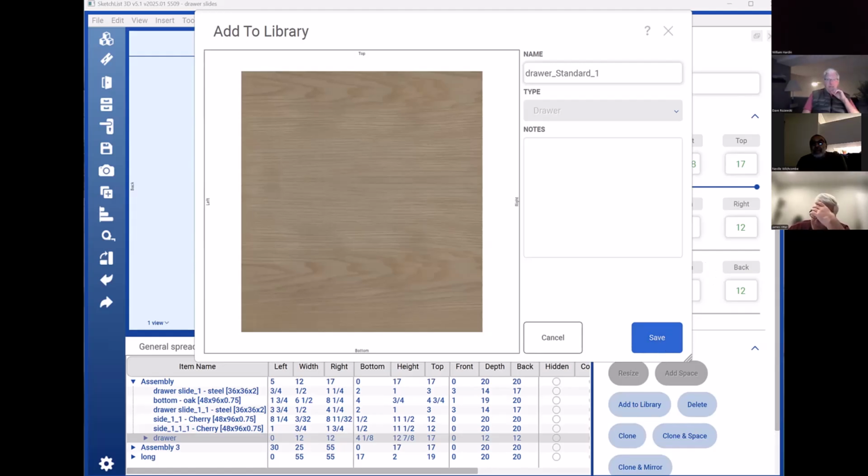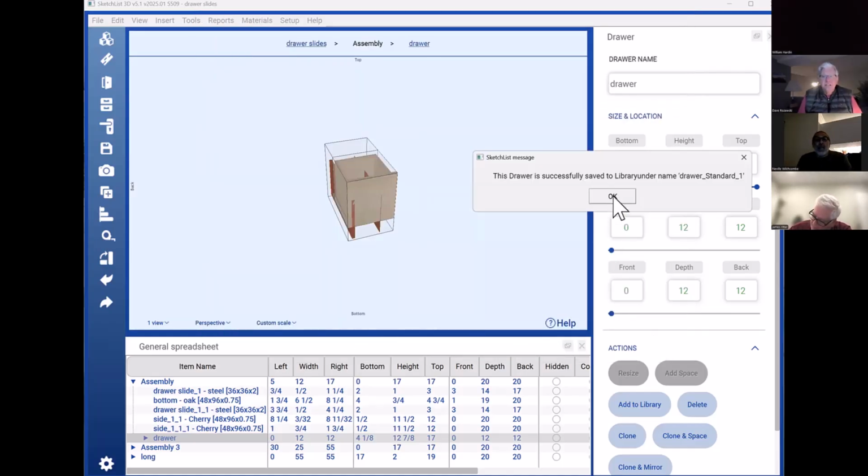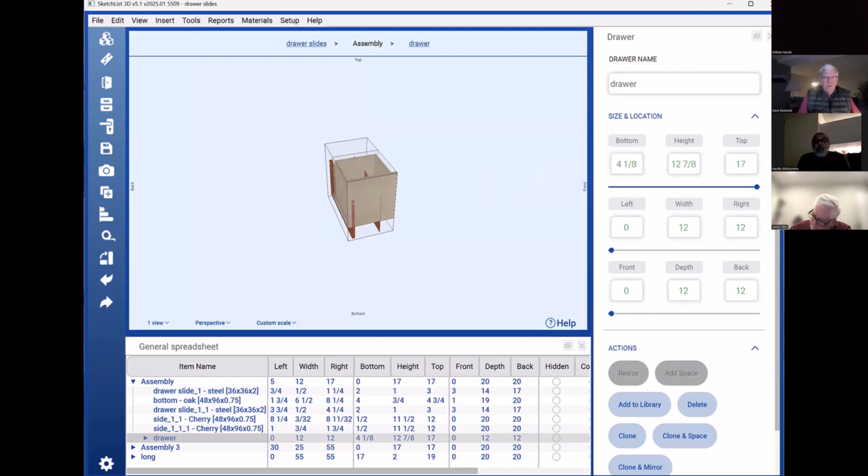Dave, while that's doing that, the system optimizer you were showing before, does that take grain direction into account? You know what? That all broke up. I just heard static. Can you repeat it, please? The optimizer, when you were showing things like being able to show blade width, for example. Yeah. Does the optimizer take into account grain direction as part of that, particularly in the sheet goods? Absolutely. That's why you have to specify the grain direction. Now you have an option to say no grain direction, but honestly, I've never noticed much of a difference, other than how it looks when it's done.